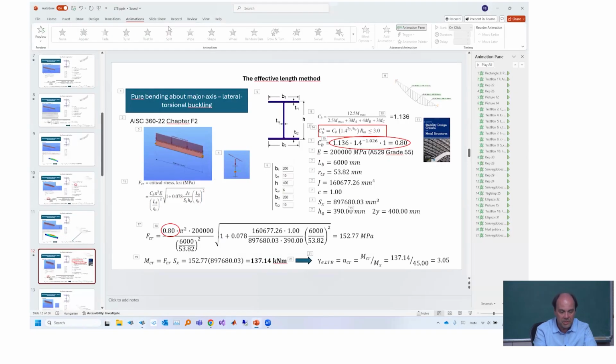Now, how can that be considered by AISC? It's not very well known, I think, to most people, but there is an additional book often referenced, the Stability Design Criteria for Metal Structures. That book contains a lot of subjects which are not found in the code or in the commentary section of it. For example, there is a combined formula to consider the effect of load height, and in addition whether there is double curvature in the bending moment or not.